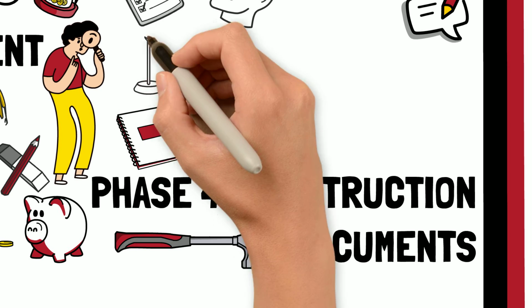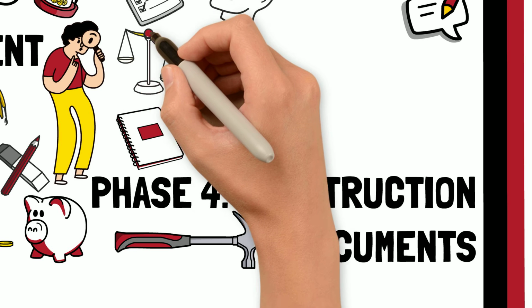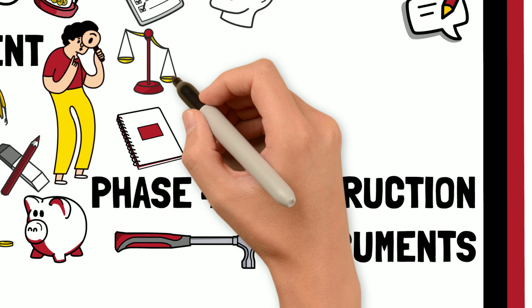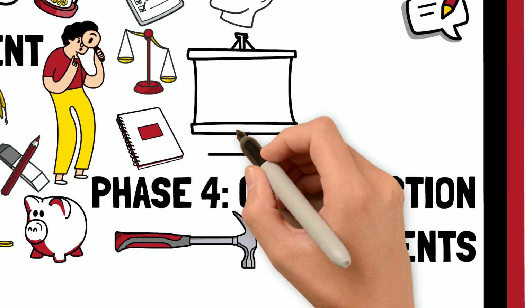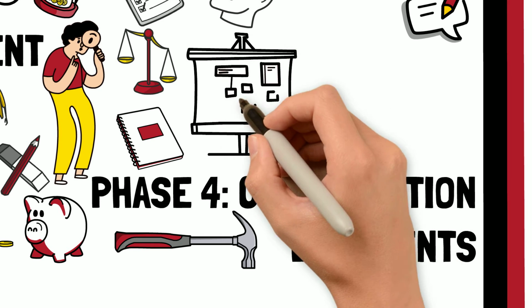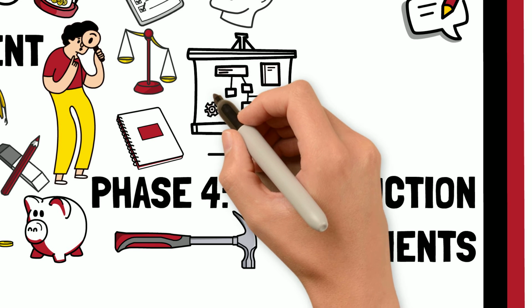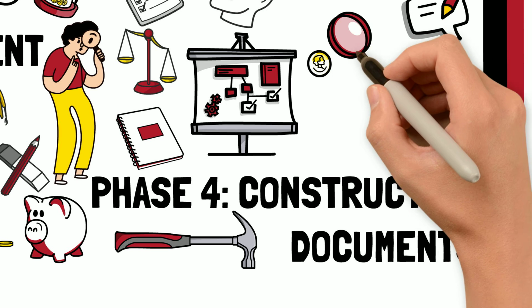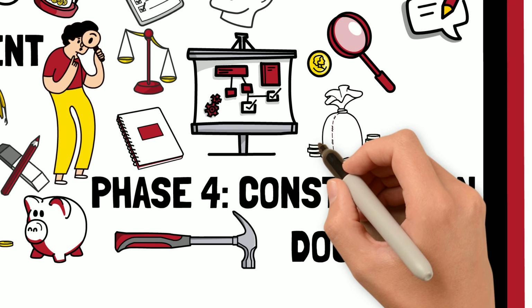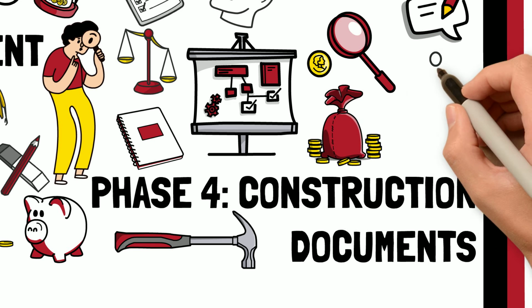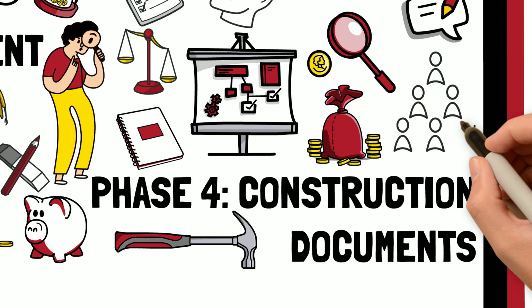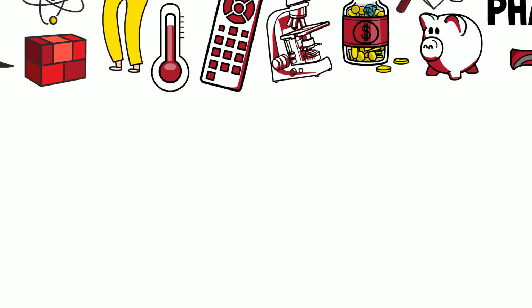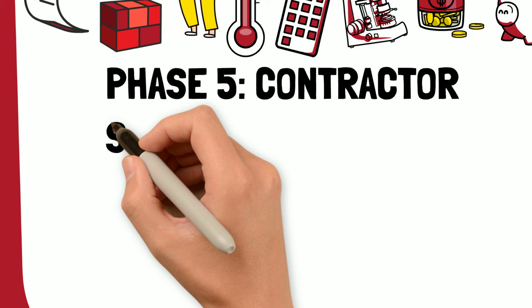Before beginning this phase, you'll discuss with your architect whether you'd like to pursue a bid price contract or a negotiated contract, and they'll craft the drawings and level of detail in those drawings based on that decision. Once you reach the construction documents phase, even the smallest change can mean spending a lot more money, because it's likely that the other consultants working on your project will have to make changes to their parts of the design as well.